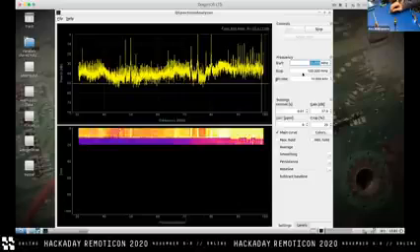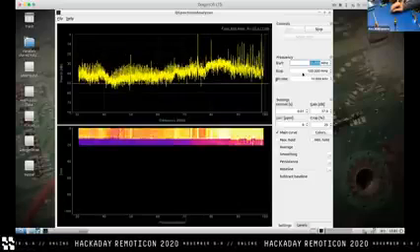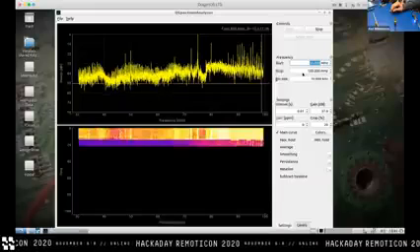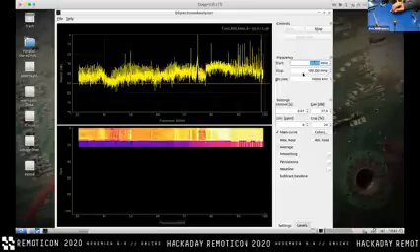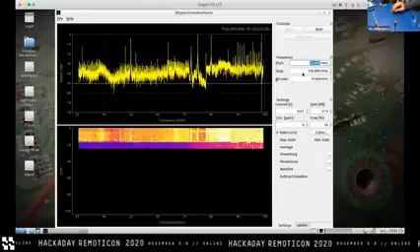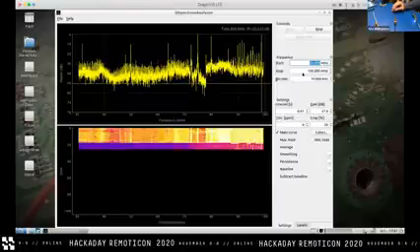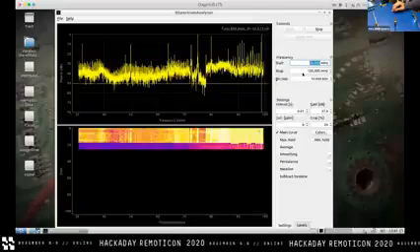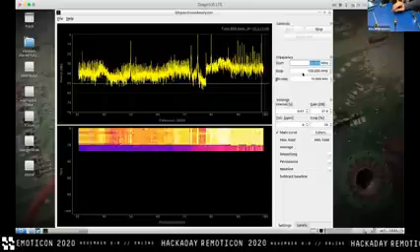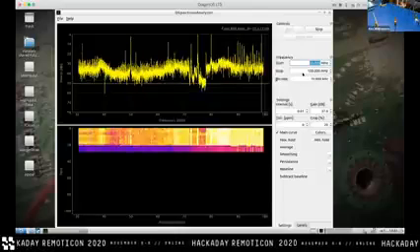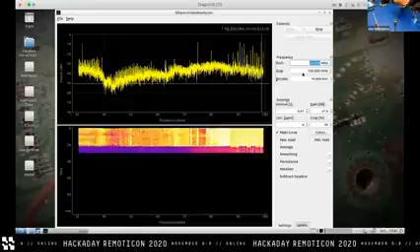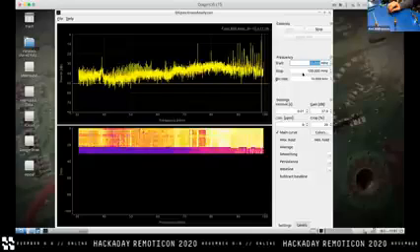And obviously the disadvantage of doing this, and this is where your cost constraint is a trade-off between features and convenience and money, is that this updates one chunk every couple of seconds. It tells us what's going on everywhere in the spectrum, but not everywhere on the board. If I wave my wand around, whatever section of the spectrum it happened to be sampling in that time, we'll get caught. So I'm going to click it and then take my sample away, and we're going to see weird sections of the spectrum have changed, and not all uniformly.